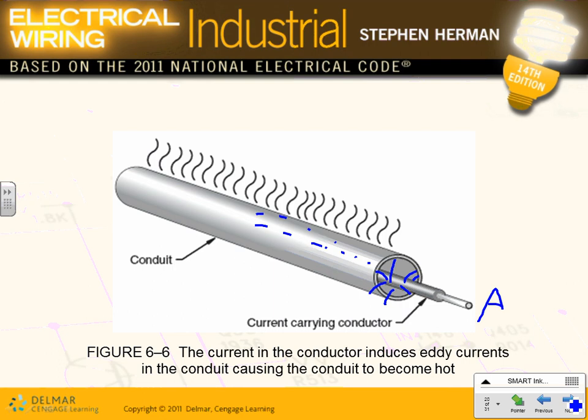And there are examples, guys, of glowing conduits because of this. And we're not talking about 5 amps here. We're talking about 100, 200, 300 amps going right through that conductor, and you're putting it in the steel conduit. It will induce enough current and voltage into the conduit, and the current is going to go everywhere.